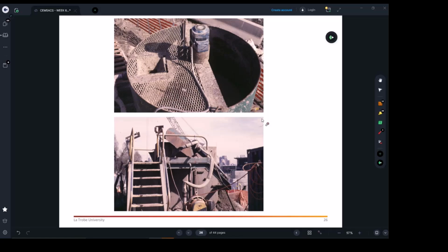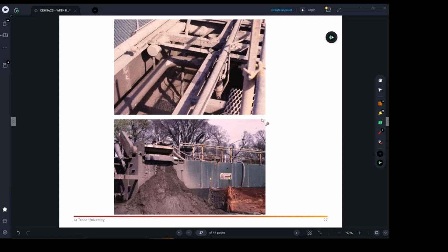As we said, at some stage, when you start pouring the concrete, almost at the end of the process, the bentonite will be pushed out from the hole, and usually that bentonite will be collected in the holding tank, where you will need to filter and clean it again for reuse. So that's the holding tank for the bentonite.